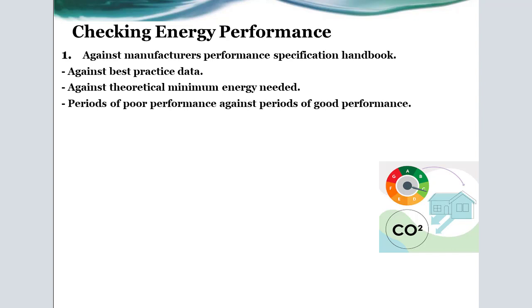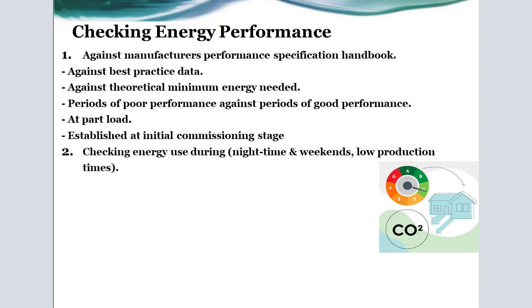Also against the period of poor performance versus the period of good performance, and also make his checking of energy performance at partial load, and also need to establish at the initial commissioning stage, and also check energy use during night time, weekend, or low production times, and so on.